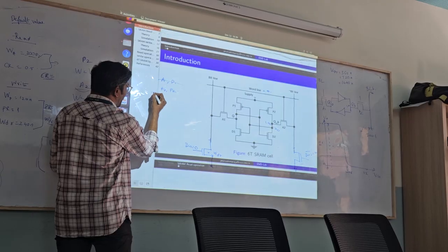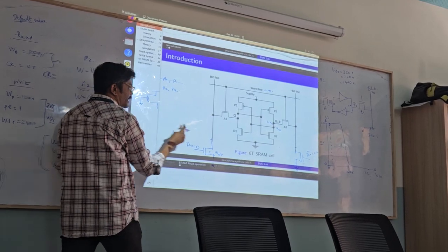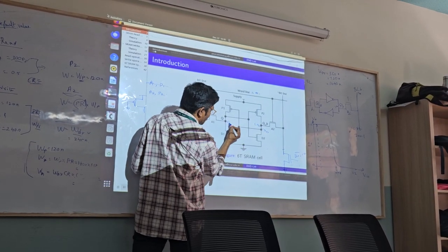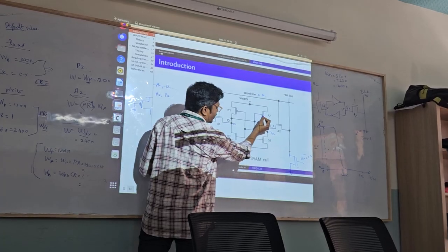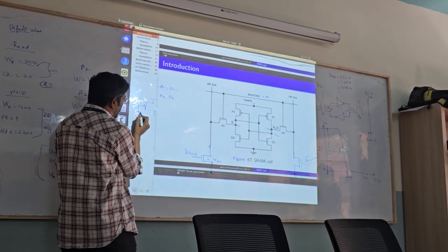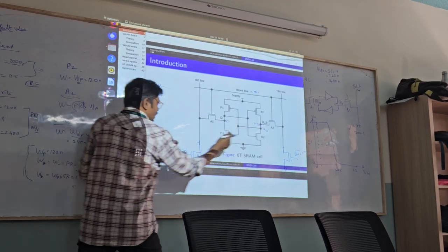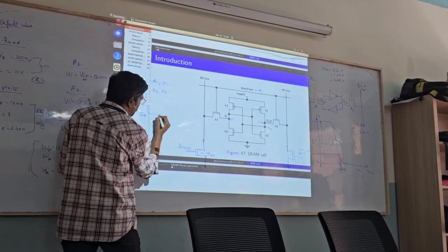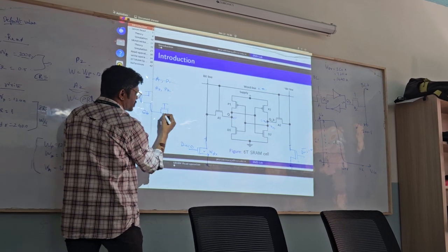So I have this P2 transistor, which is a PMOS, and that is being connected to a 0, because I had a 0 here connected to the gate of my P2. So I model that as a ground here, and then I have this A2 transistor which is connected between Q bar and the bitline bar, and that's being connected to VDD, which is modeled like this.